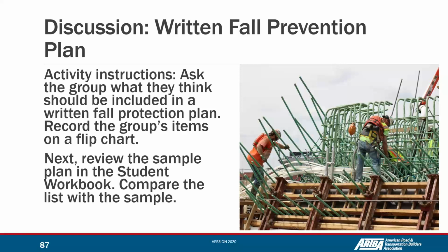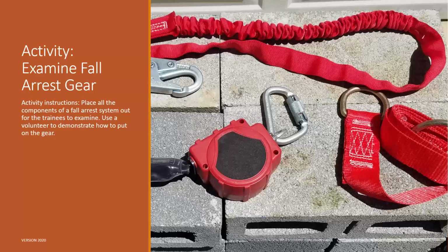Of course, we have to include the emergency rescue plan. If there is any worker falling, we need to provide rescue as soon as possible, as described before. Also, we have some activities with our students. We do the demonstration about how to use the personal fall arrest system and the parts of the personal fall arrest system. We identify all the engraved parts in this personal fall arrest system.